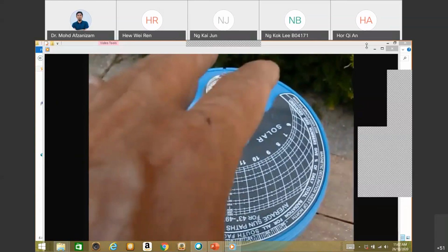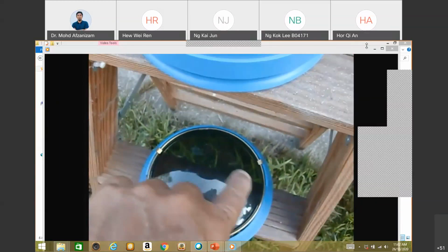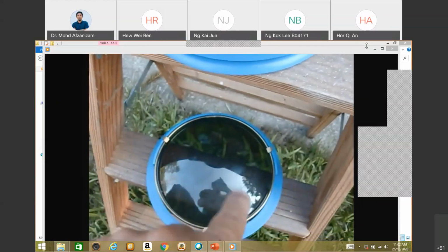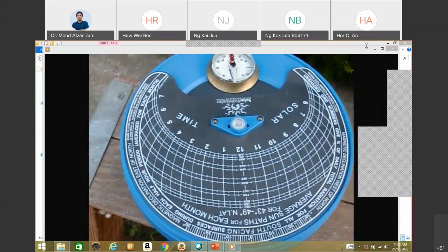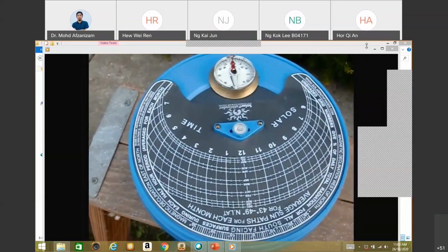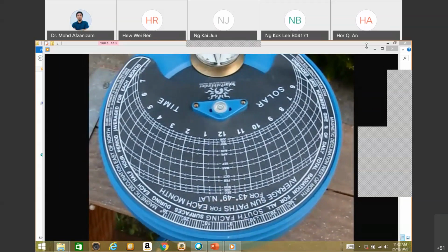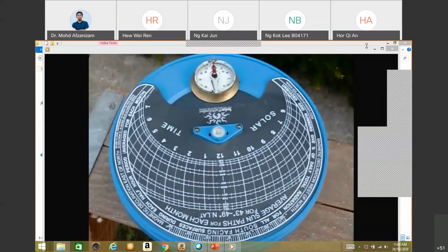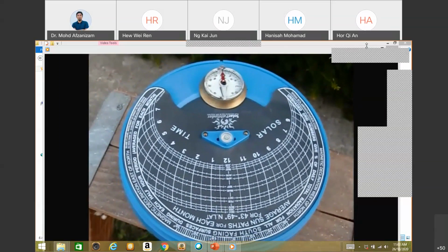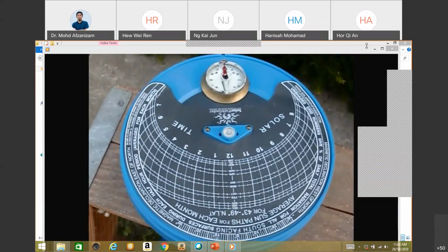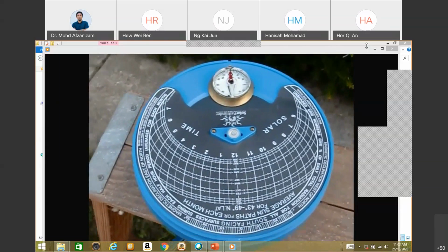And what I'll do next is put a reflective dome over the top, and you can see the dark areas will reflect the shaded or dark spots. The light areas is where the sun is coming through. And you can use this along with this chart here to actually predict what percent of sun you're going to get through every month of the year at this location. And you put different rates on here based on the latitude. I'm falling in the 43 to 49 north latitude range. You also make slight adjustments east to west based on the difference in the magnetic heading compared to due south. And where I'm at, it's very close to right on the zero magnetic declination line. So let me put the dome on. I'll show you what that looks like.